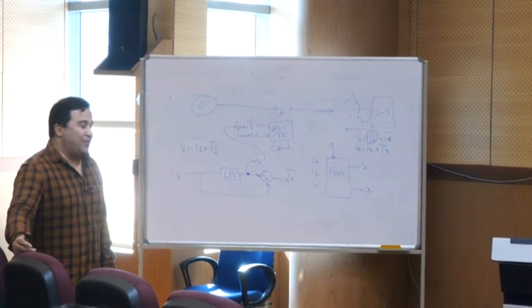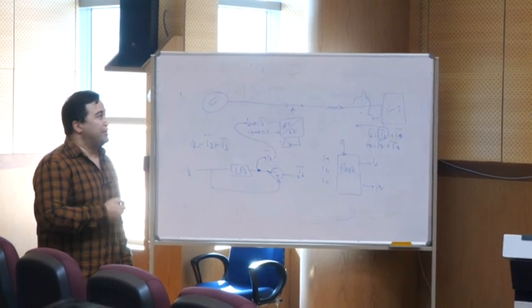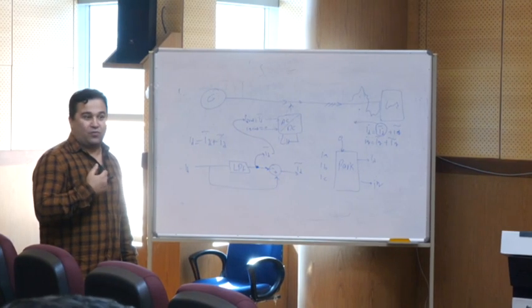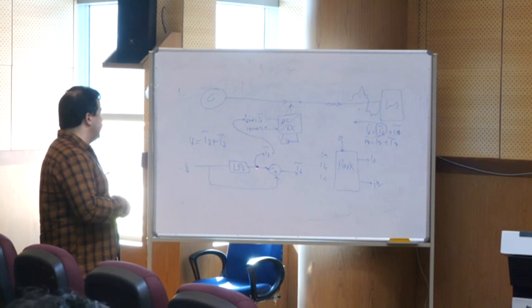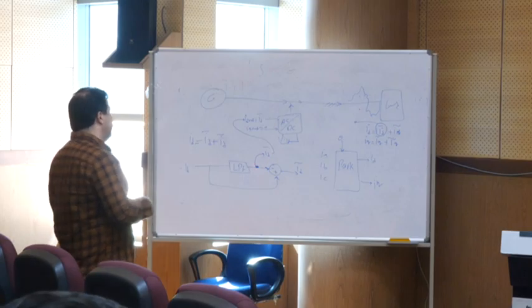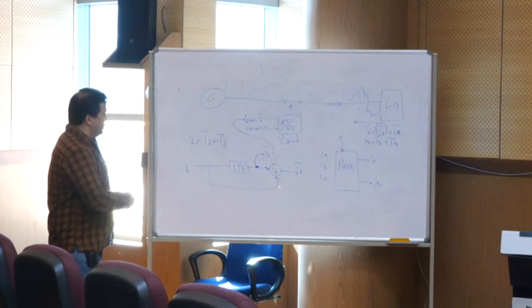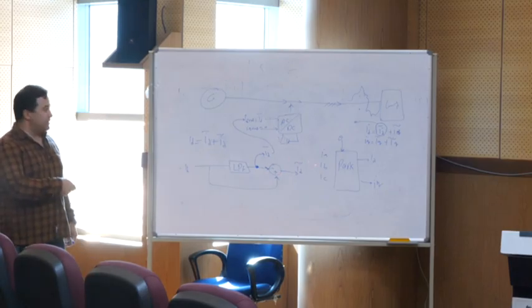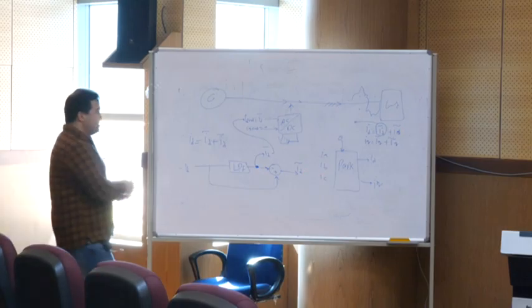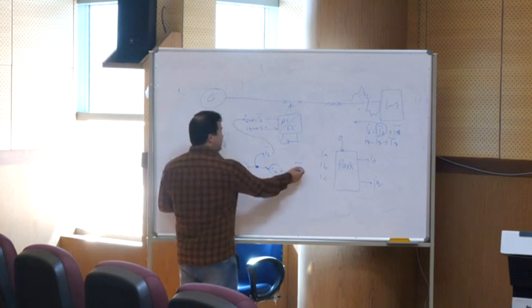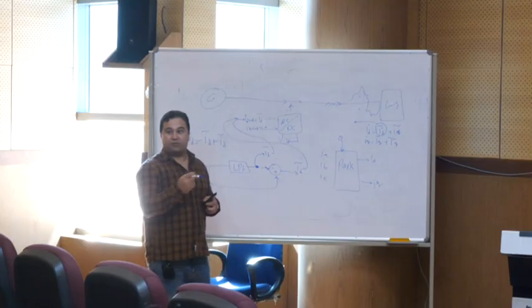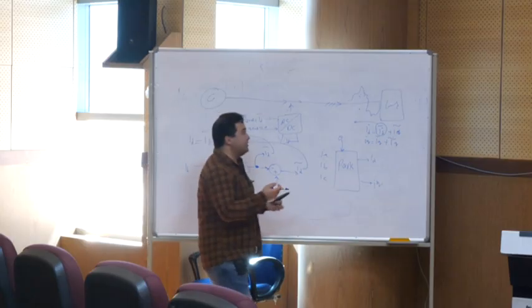Okay, now we go to the next part: calculation of the harmonic component of the reference current. When we have this filter, we have the DC value, then we use the original current minus the DC value, and the rest will be harmonic. So if we consider this as a reference in the axis, in fact the converter provides all the harmonics for the load.